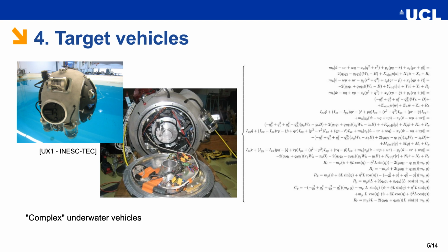This vehicle can be, of course, modeled with a set of nonlinear ODEs, but as we said before, the model quickly gets really convoluted to implement in a standard causal analytical simulator. As you can see on the right-hand side, I modeled this vehicle with a system of 12 ODEs, covering the 6 linear and angular accelerations of the vehicle hull and the 6 linear and angular accelerations of the internal pitching mass. There is an exchange of reaction forces between the two bodies, and this type of occurrence often gives rise to algebraic loops, which, as I mentioned earlier, are not always easy to break.